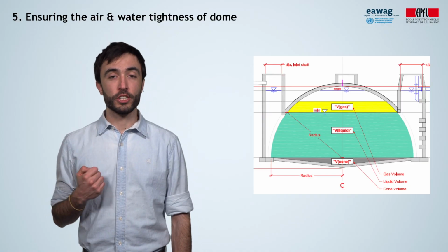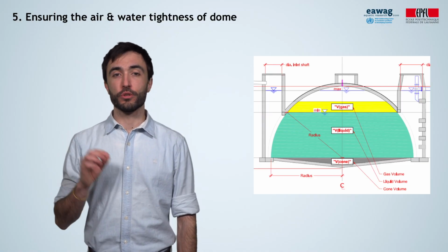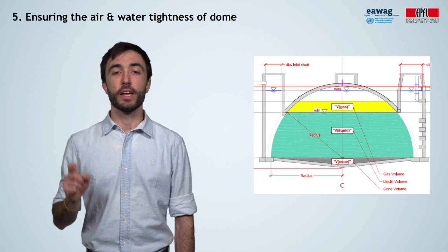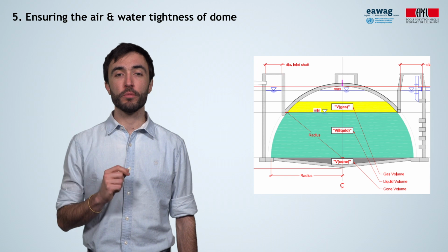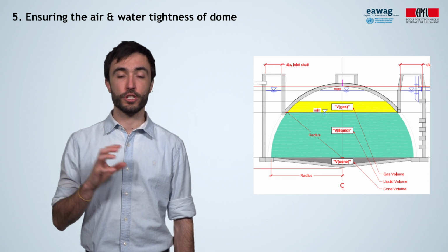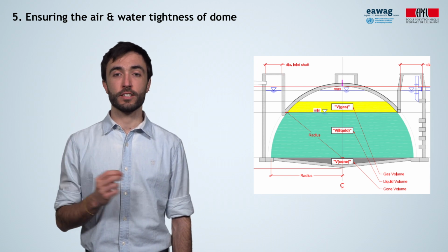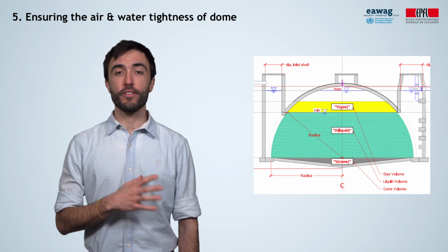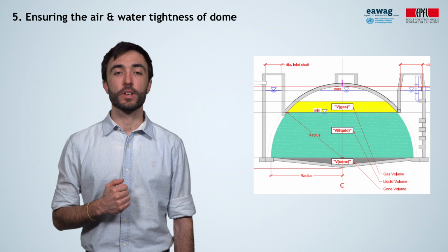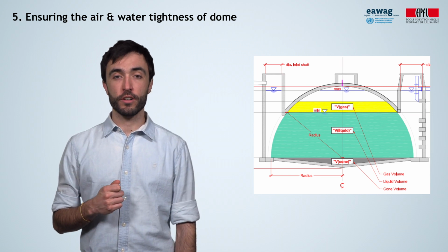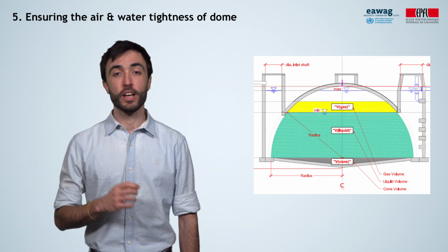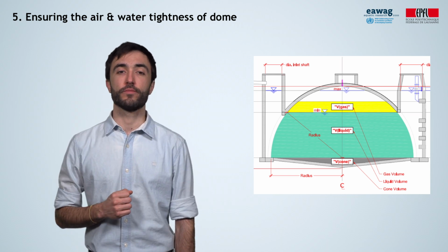Once the dome is finished, the next step is to ensure the air and water tightness of the reactor. It is important to mention that the main problems that these sort of digesters present are related to the gas tightness of the brickwork or the cracks causing heavy losses of biogas. Fixed dome digesters are, therefore, recommended only where experienced biogas technicians can supervise their construction.